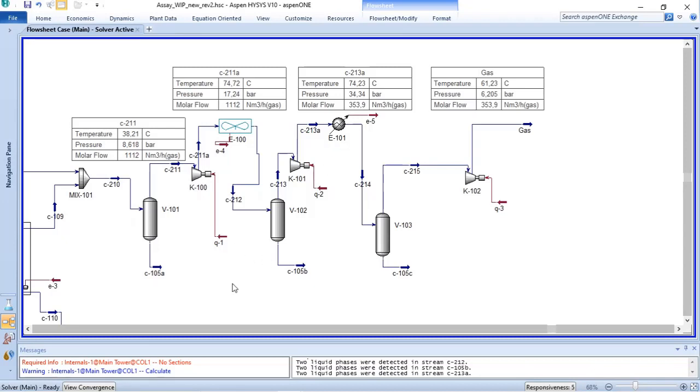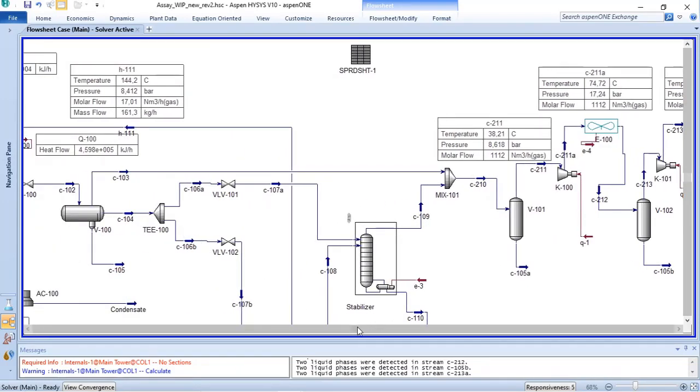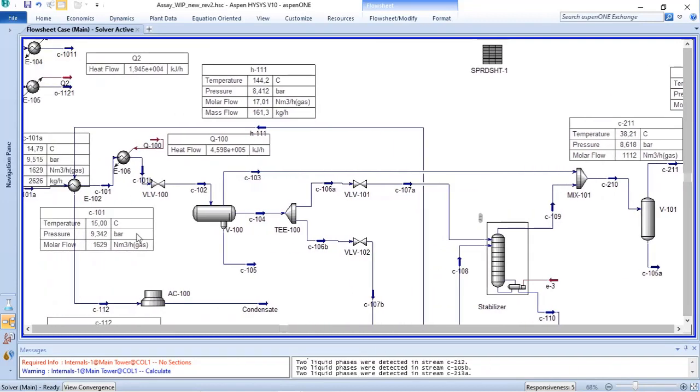And it would be a resource for our heat recovery, because instead of using the air cooler to cool down the compressor discharge, we could recirculate that to the preheating, and in that case save some energy in the electrical heater.